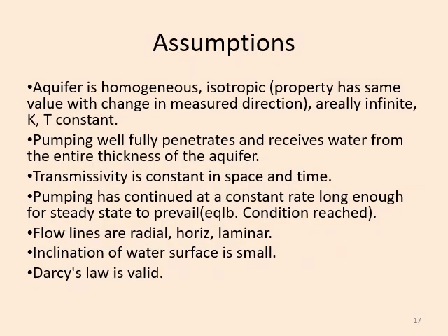So the assumptions we are taking here are that the aquifer is homogeneous, isotropic, the areal extent is infinite, and K and T are constants. Coefficient of permeability and transmissibility are constant.